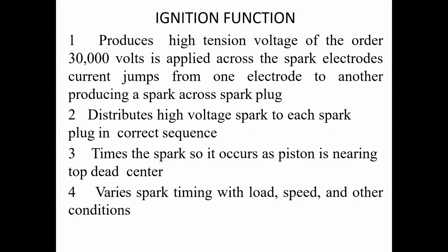I was also quoting the length of the spark gap, which I am going to show you. In the practical case also, the spark gap length should be between 0.9 and 1.5 millimeters. So what happens if the spark gap is below 0.9 or above 1.5 millimeters? We'll discuss what happens.